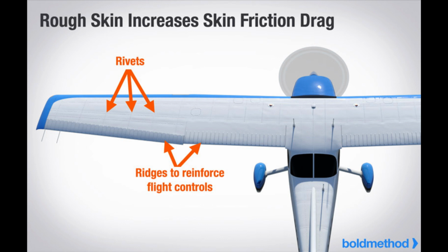This speed is called the freestream velocity. The area between the wing and the freestream velocity level is about as wide as a playing card and is called the boundary layer. At the top of the boundary layer, the molecules increase velocity and move at the same speed as the molecules outside the boundary layer. The actual speed at which the molecules move depends upon the shape of the wing, the viscosity, stickiness of the air through which the wing or airfoil is moving, and its compressibility, how much it can be compacted.